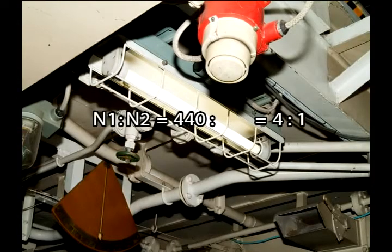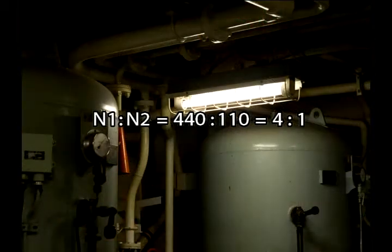Let's now look at the voltage used for lights on board a ship. When the generator voltage is 440 volts, a voltage of 110 volts for inboard lights can be obtained by setting the ratio of primary turns to secondary turns as 4:1.